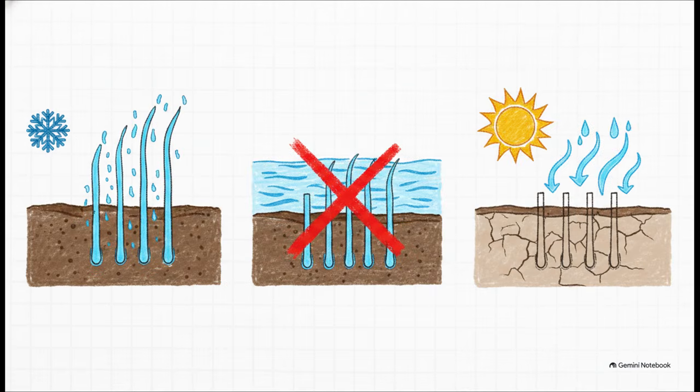You know, this whole incredible balance is also highly sensitive to the environment. For instance, a drop in temperature actually increases surface tension, which makes the water climb even higher in the cold. Conversely, if a flood fully submerges the area, capillarity stops entirely, just ceases, because that crucial air-water interface is totally gone. And on hot days, evaporation at the surface constantly pulls that highly mobile capillary water up and out of the ground, continuing a relentless cycle.